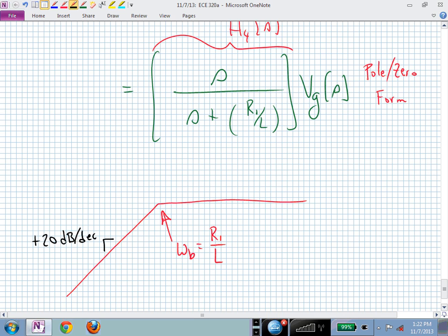And at high frequencies, does this make sense? What happens in this picture at high frequencies? In the denominator, the S term dominates, doesn't it? And in the numerator, I just have an S. So I now have S over S, and they're both going off to infinity together. Your gain is 1, isn't it? So in dB, that's 0 dB. Are we getting the feel of this? Why you want to know about limiting behaviors, etc.?